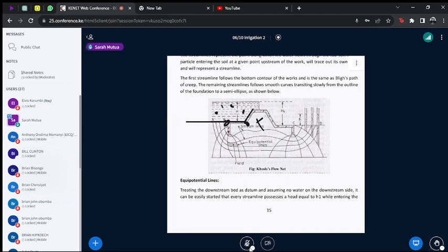As the water flows, the equipotential line now varies downstream so that water can flow. And you can see it is kind of in a cyclic direction. And you are going to get, therefore, such kind of lines, equipotential lines and what have you. You can see this equipotential line here, whereby some piezometers have been installed just to show that for equipotential lines, the energy, the hydraulic head has to be the same.